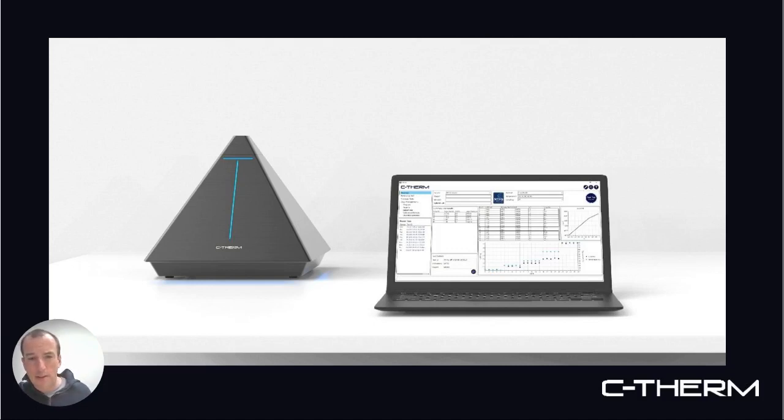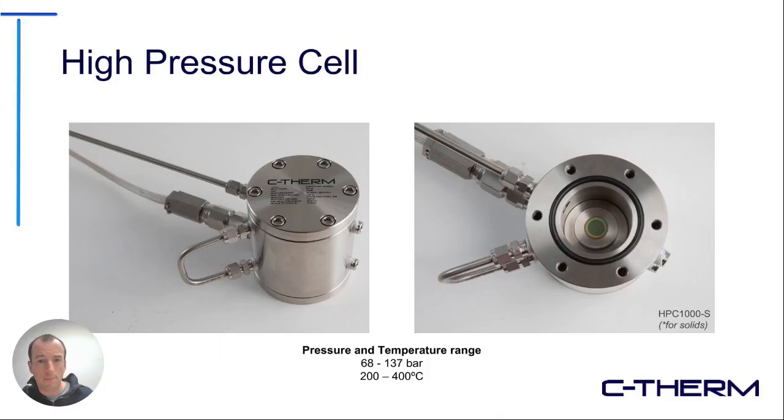We'll also record in that measurement the temperature at which the sensor is based, and the thermal effusivity of the material. With effusivity, we can then derive other properties indirectly. So if you want to understand the heat capacity of your material, we can look at that indirectly based on the relationship between the effusivity and the conductivity of the material with an inputted density. Effusivity is the square root of the thermal conductivity, density, and heat capacity. So it can be used to leverage other thermophysical property data on your material.